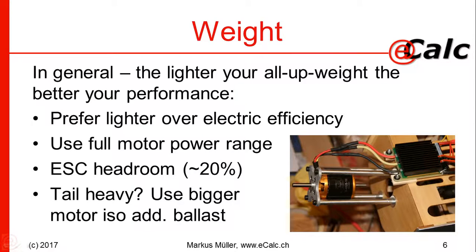Then always use the full power range the motor offers. At full throttle you should reach the limit of the motor. For the ESC I always have 20% headroom, and should your aircraft be tail heavy, just use a bigger motor instead of additional ballast.